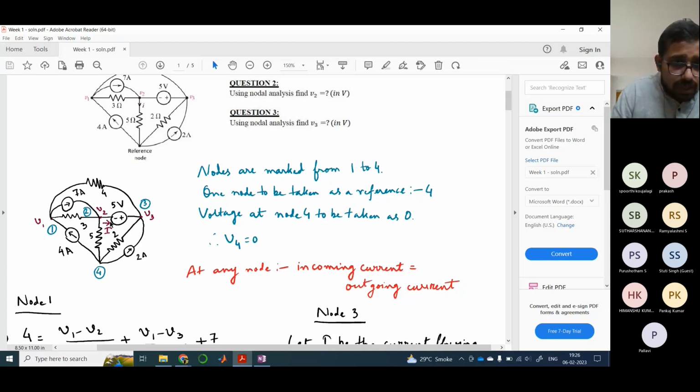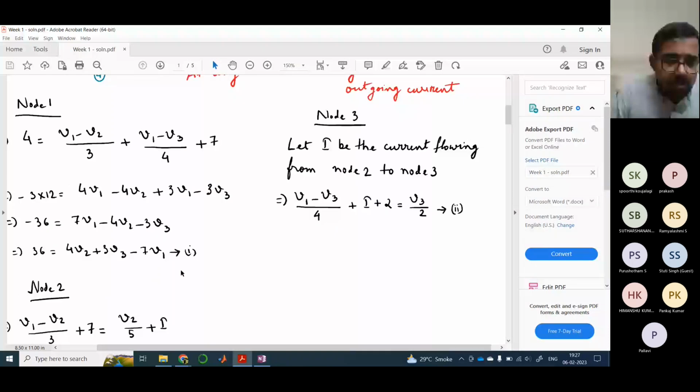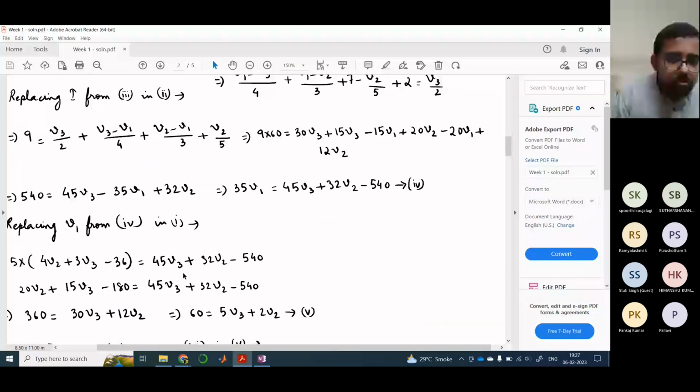This is because, guys, just look at the direction in which this plus and minus is placed. This minus is pointing towards node 2 and this plus is pointing towards node 3, right? Therefore, the potential at node 3 is higher than the potential at node 2, because this plus is pointing towards V3. By how much? By a value of 5. Therefore, we write V3 equals V2 plus 5.